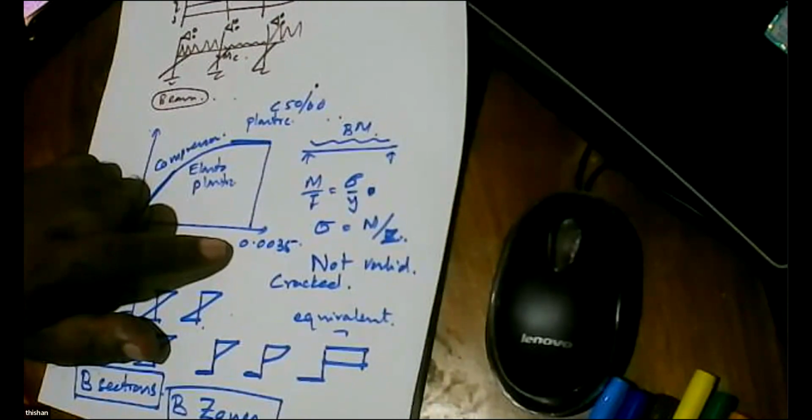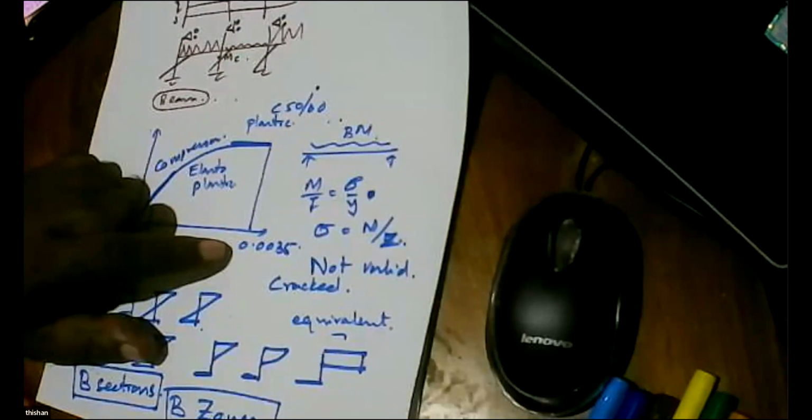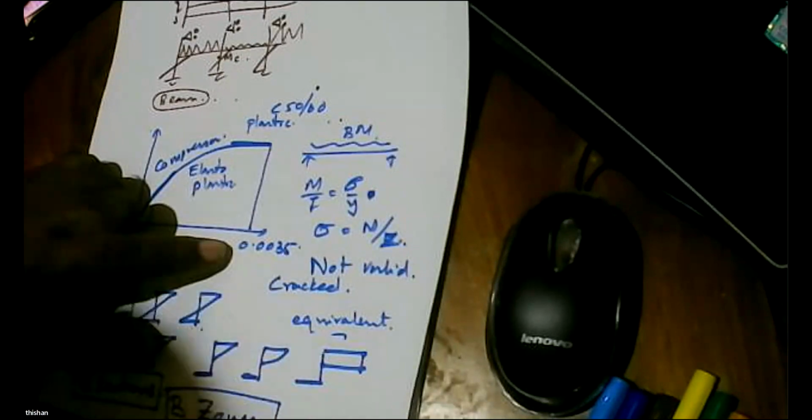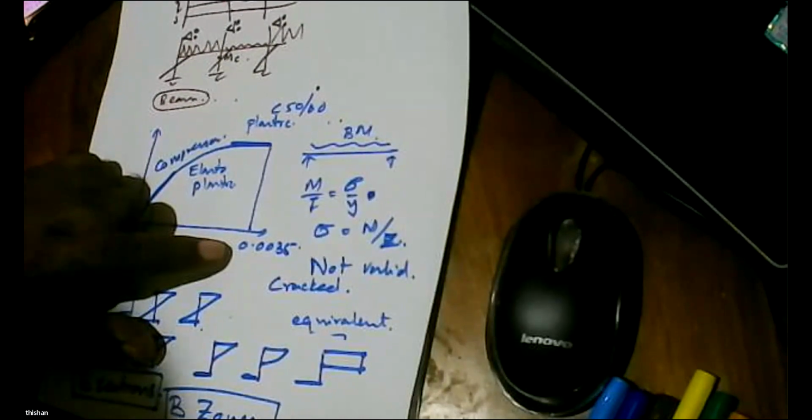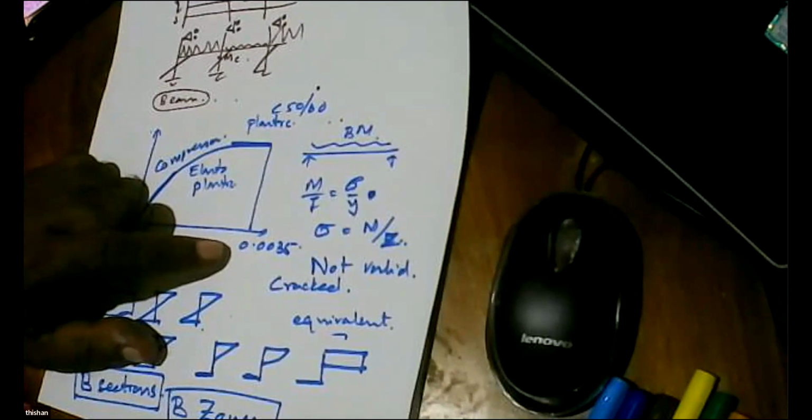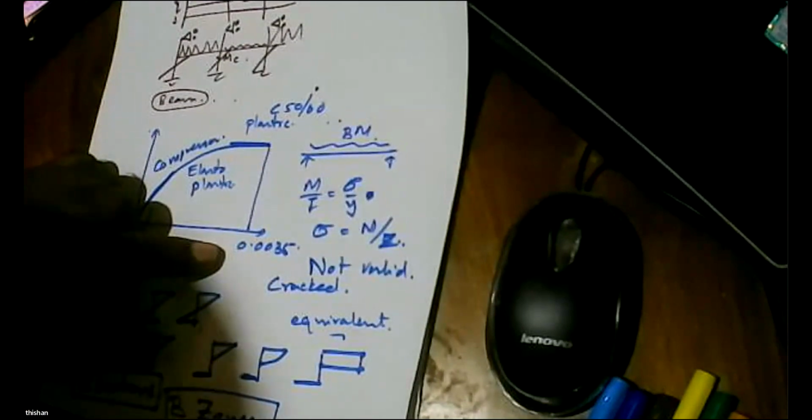But theory is theory. But people did not know about this theory called D zone. So they said, okay, strut and tie. Because the test results do not comply with the beam theory. They give different results. So they came up with strut and tie, which gives a better result. But they were not explicitly telling us. They said, okay, if it's a pile cap, you must use the strut and tie method. If it's a corbel, you must use the strut and tie method. So they were giving the solution, but not explaining the problem adequately.